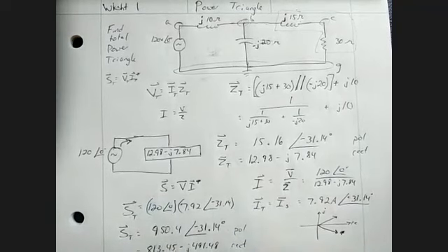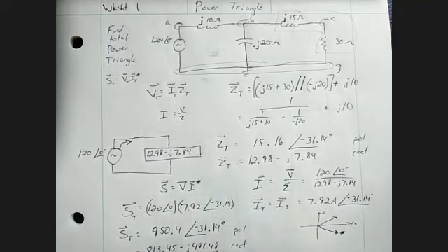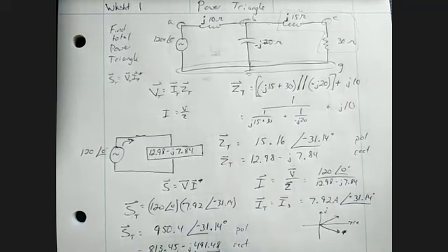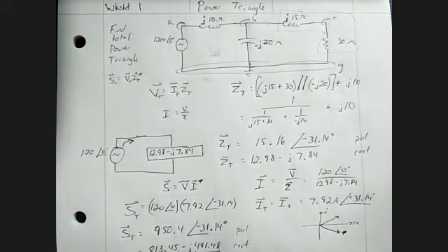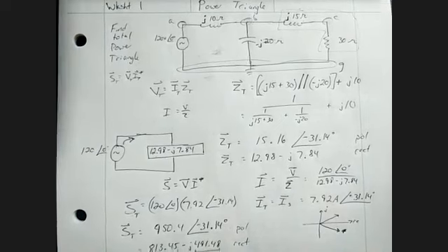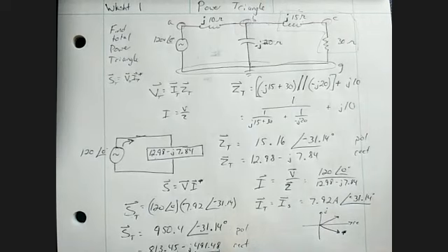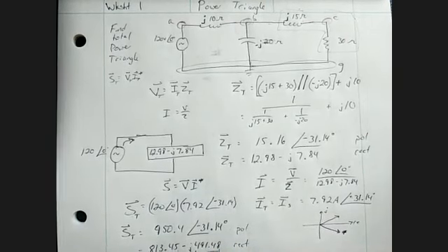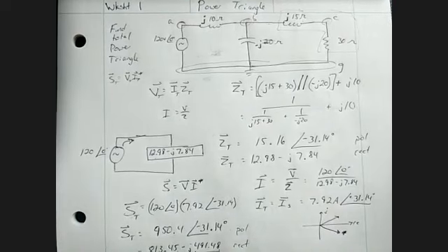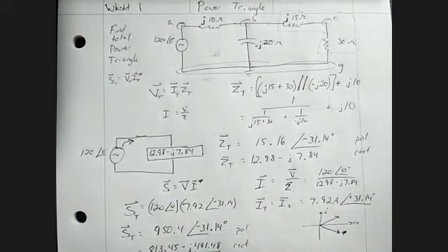This right here is the real power. This right here is the reactive power, Q. If I'm forming a triangle, this P is the real axis. This is a negative Q. This is also a negative angle, here's about 30. There is my Q: 491.48 volt amps reactive. P: 813.45 watts. Real power, watts, just like it was in DC.